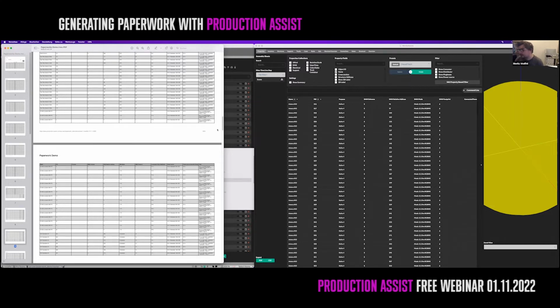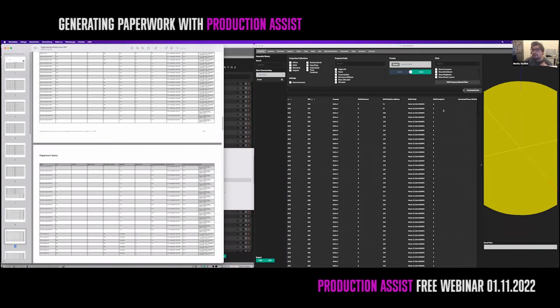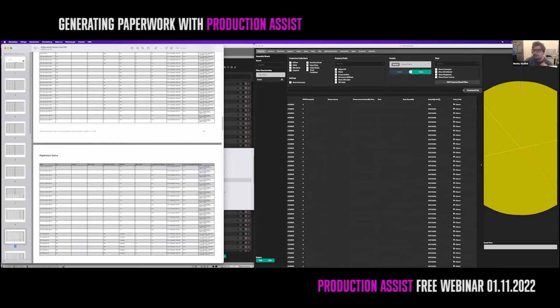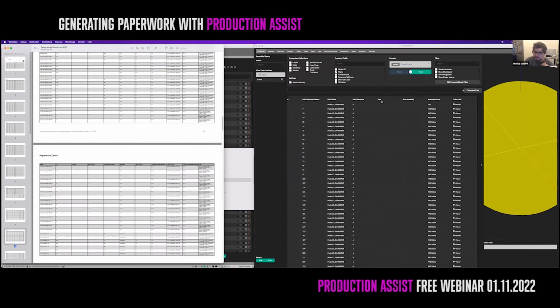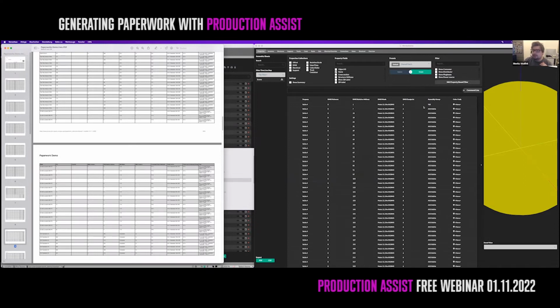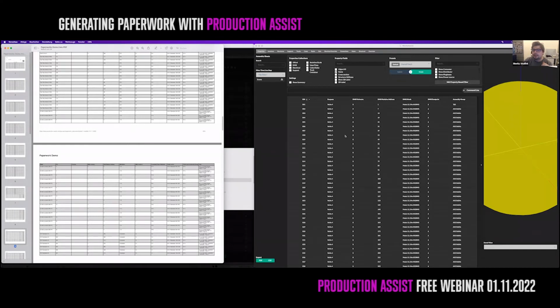This paperwork now has really too much information, so we want to reduce it. The first thing to reduce this is that you can, for example, hide specific property rows. For example, we don't need to tell the lighting operator what the connected power distributor is, so you can right click on it and remove the column. We don't need the power source in here, so remove the column. The power source assembly group, we don't need it. The fuse we don't need. The fuse assembly we don't need. The assembly group makes sense for classing, so let's keep it, but we will remove the column in here. So it's really easy to change this.